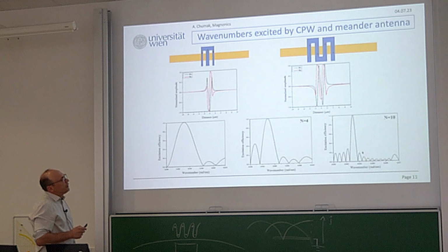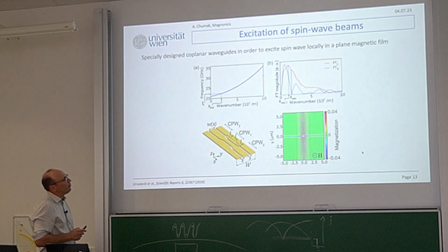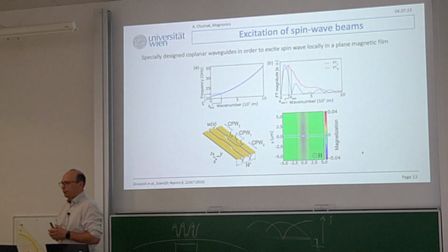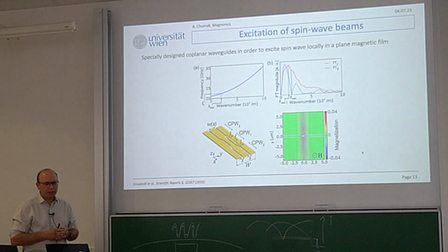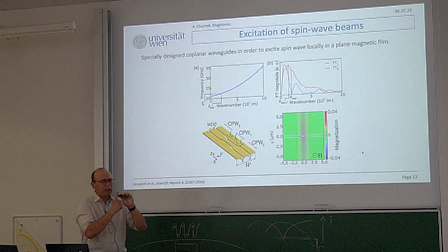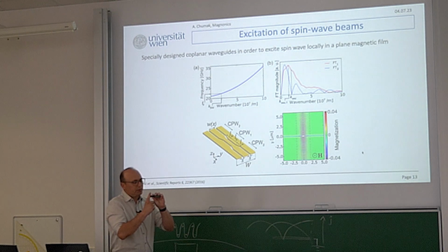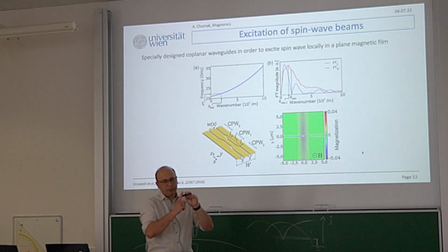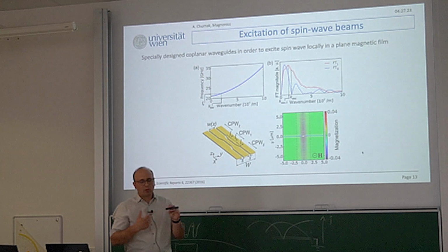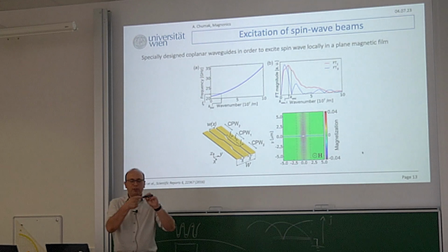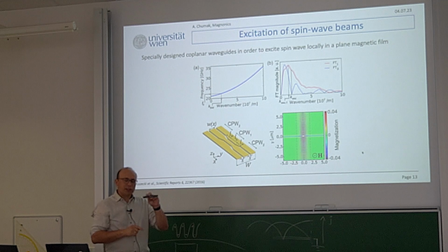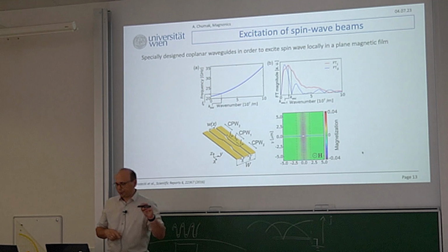So much about nanoscale, and now imagine that you work not with a waveguide but with a plain film, so there is no structure. And in reality, it's much more complicated. So with a waveguide, why it's comfortable to work with: as soon as you have excited a spin wave here, it doesn't matter which mode it has, which property, which group velocity, and so on, because spin waves are usually complex. They can have different group velocities in different directions. There is the so-called acoustic phenomenon and so on, when it propagates from a point source not along all directions, but in the form of some beam. But as long as you have a waveguide, it always runs along.